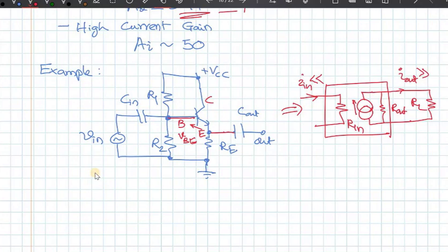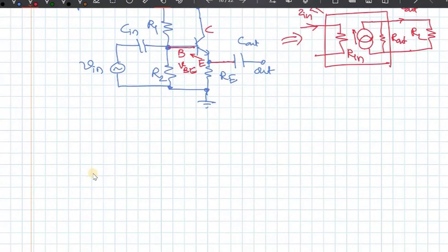Sometimes this is called a buffer, because in computer applications there are a lot of cases where the digital lines cannot provide the current, but they just maintain the voltage. So if you want to use a signal from it to control something, you need to send it to a buffer, which can provide the current capability. So that is why it is called a buffer. This is often used as a buffer circuit or a voltage follower. We sometimes call this a voltage follower also, which means the voltage is the same, it doesn't change.